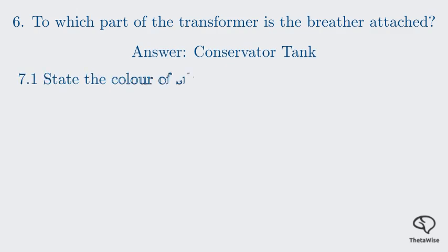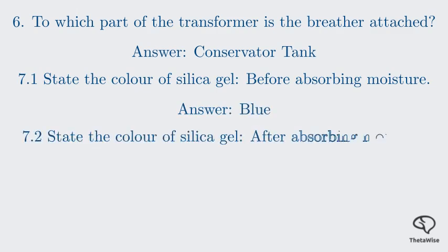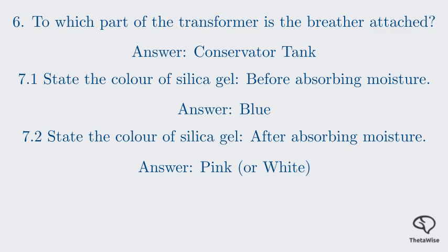Next, question 7 asks for the color of silica gel. Before absorbing moisture, it is typically blue. After absorbing moisture, the silica gel in the breather changes color, usually to pink. This serves as a visual indicator that the gel is saturated and needs to be replaced or regenerated.